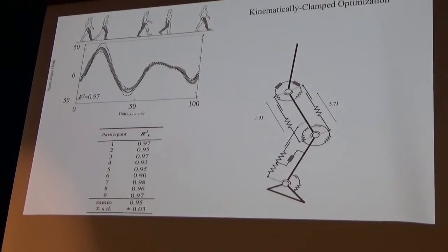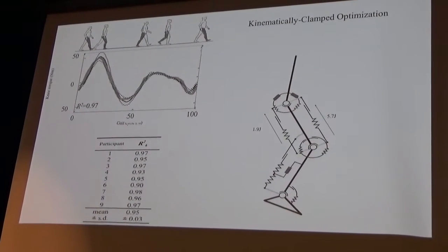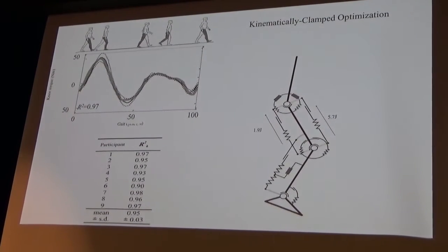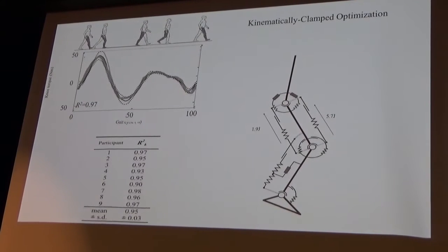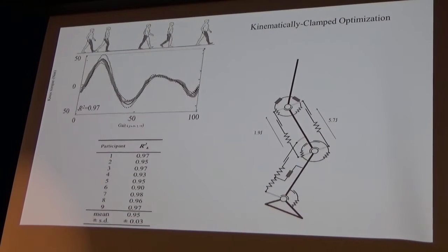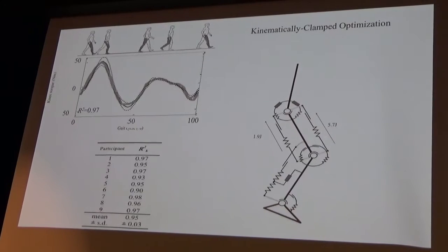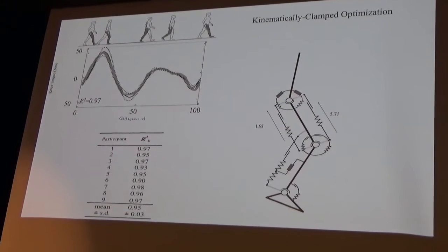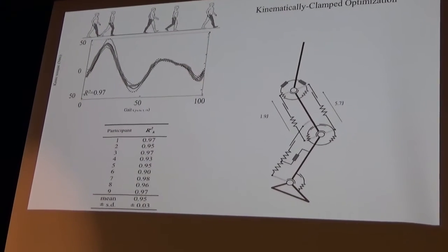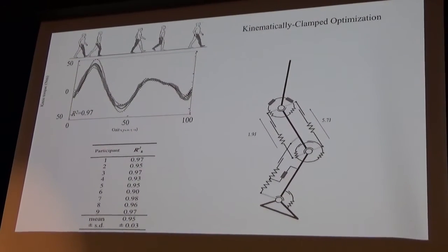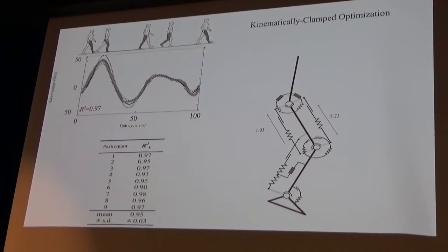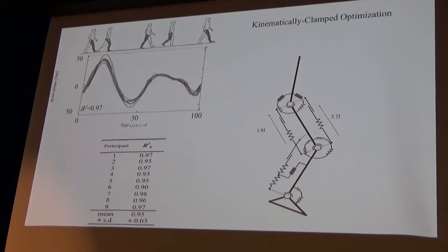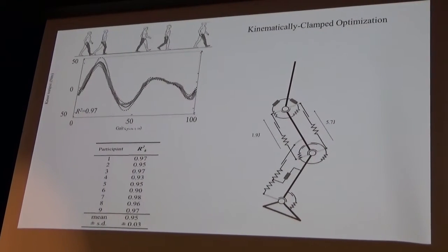So in this model, we have a simplified abstraction of muscle tendons, specifically muscle tendons that span the knee joint and dorsiflex the ankle. This is only for preferred walking speeds on a flat level surface. So the simplification is under neural control, the muscle tendon behaves like a spring. So you apply a neural command, there's a spring-like force. When you release the neural command, there's no force. So we apply that to all the muscles that span the knee and that dorsiflex the ankle.